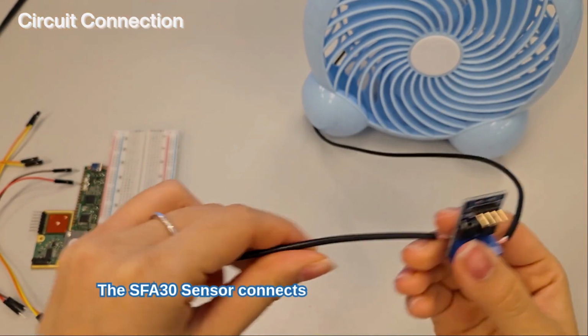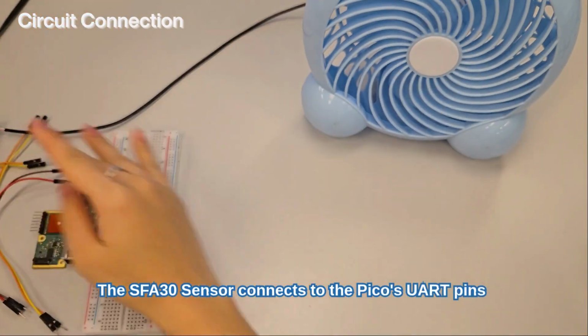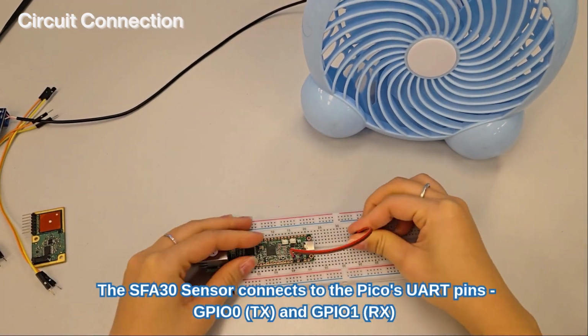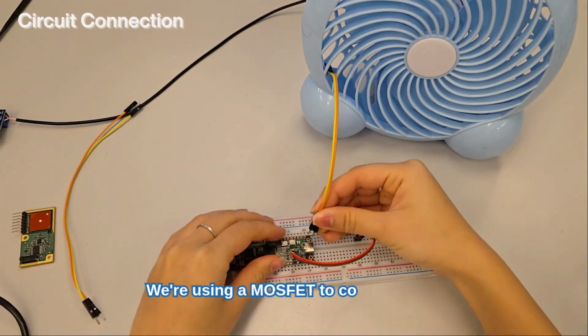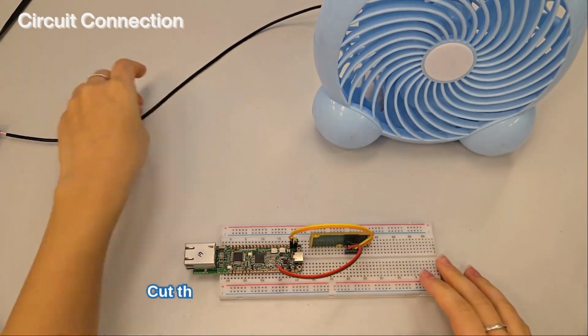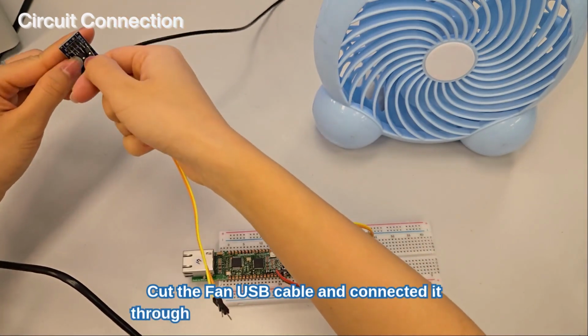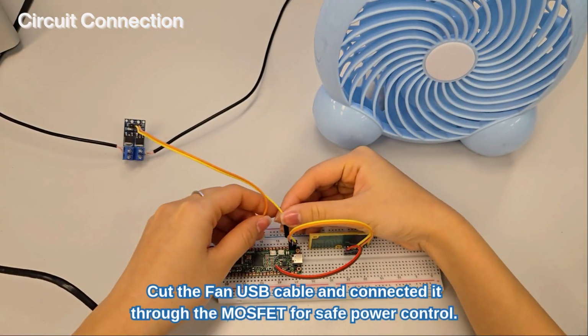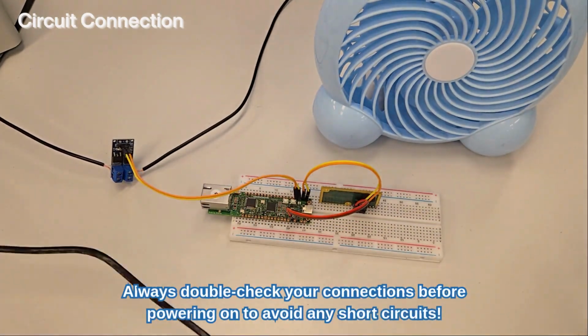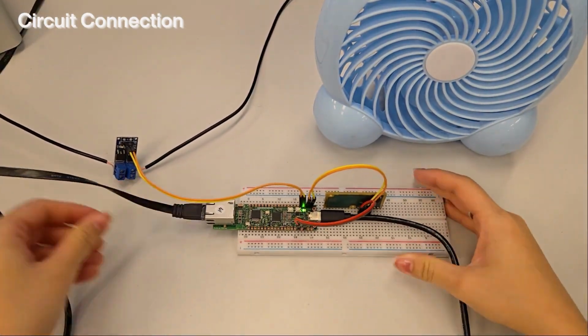The SFA30 sensor connects to the Pico's UART pins, GPIO0 and GPIO1. We're using a MOSFET to control the fan via PWM on GPIO2. Cut the fan USB cable and connect it through the MOSFET for safe power control. Always double-check your connections before powering on to avoid any short circuits.